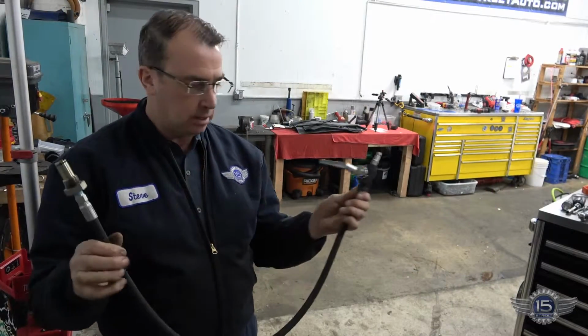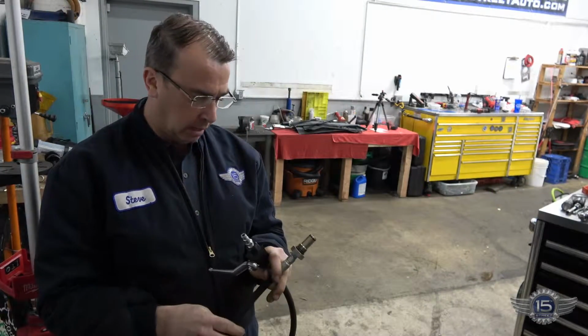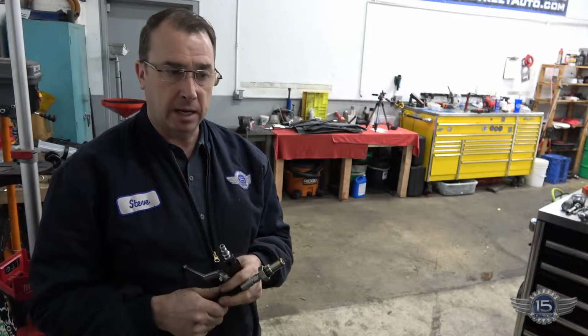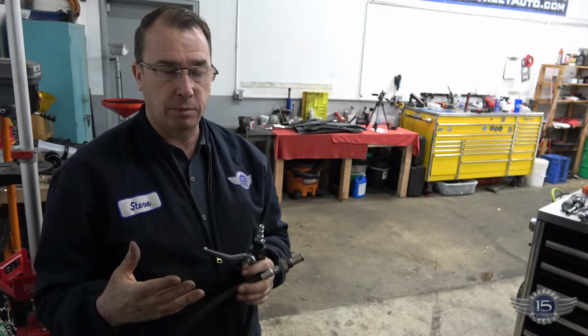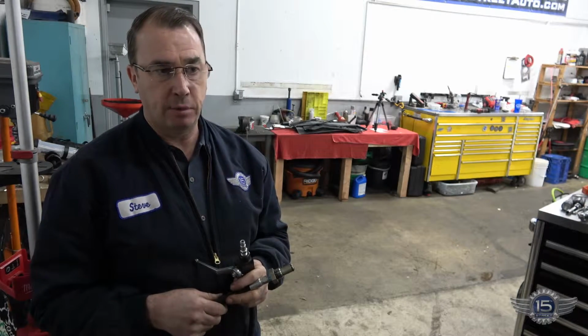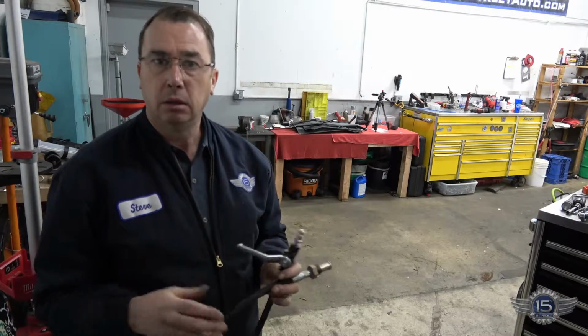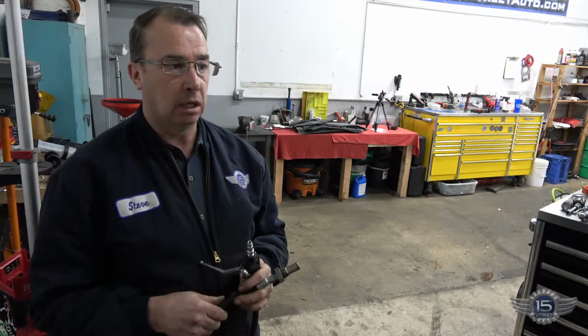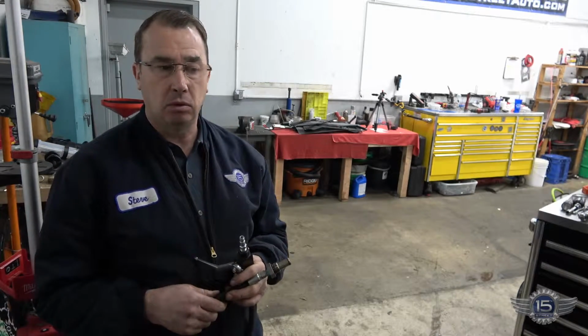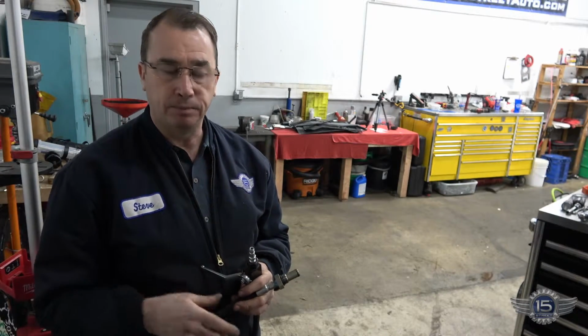Alright, so I've got a special tool here that I use on these 6-liters just for this exact problem. We've got a loss of high pressure oil pressure. It takes 500 psi of high pressure oil pressure to open the injectors. We're getting like 20. So either the high pressure oil pump is dead, or there's a leak in the system, or the pressure regulator is not doing its job, stuck open.